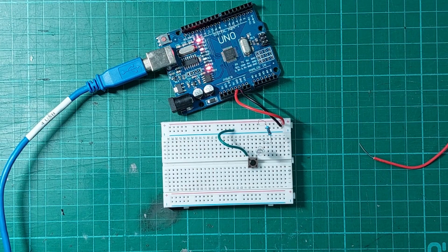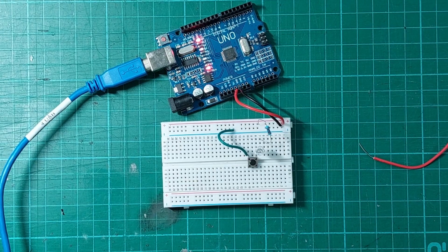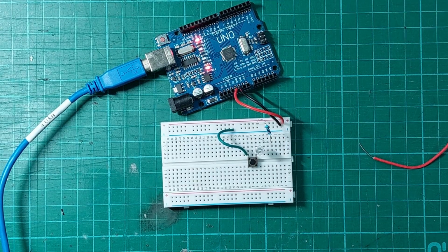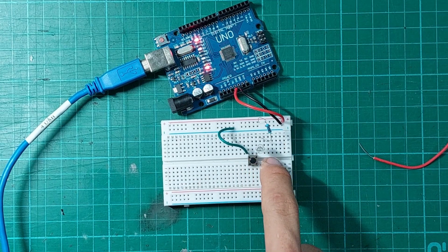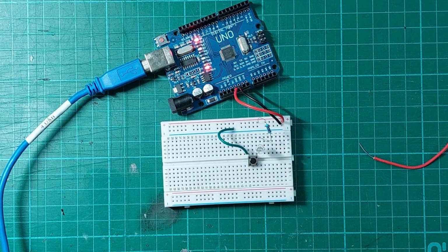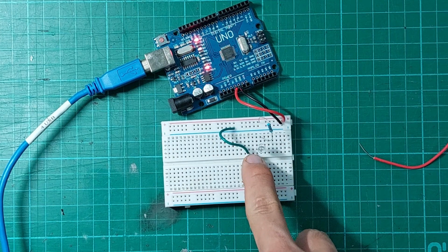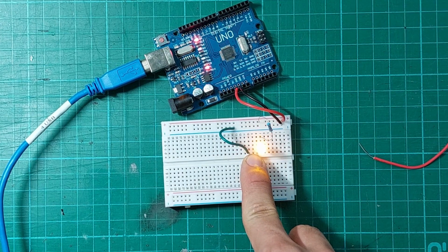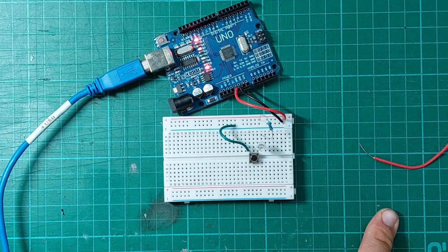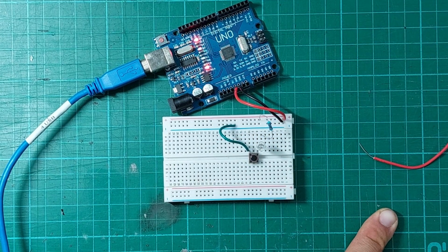So if you have watched the previous video, you would recognize this little setup that I have here. It was our simple LED circuit that we did in the first video, and I've just made one tiny change. I've added this button. So this button sits between the negative of the LED and ground, and it's going to allow me to turn on and off this LED. So if I press the button, the circuit is closed, the LED turns on. If I release the button, the LED turns off because the circuit is open.